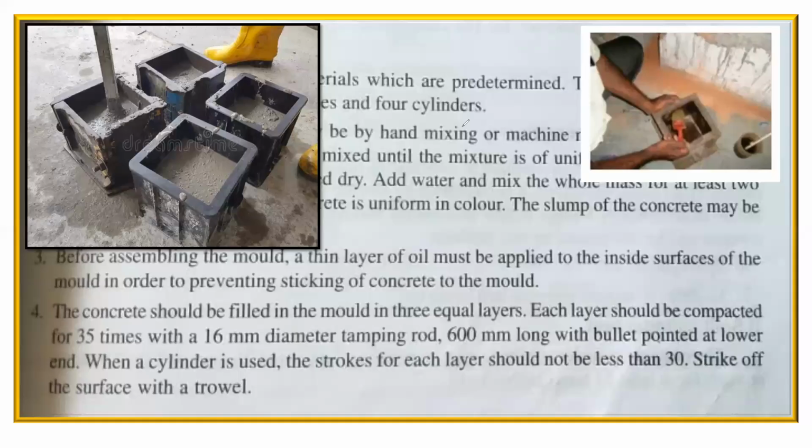So what it's trying to tell is, when you fill the concrete in the cube, you have to fill it in layers, right? So how do you decide that? If you refer to the Indian Standard Code books, it says that you have to fill 5 centimeter at a single time. So 5 centimeter will be each layer.